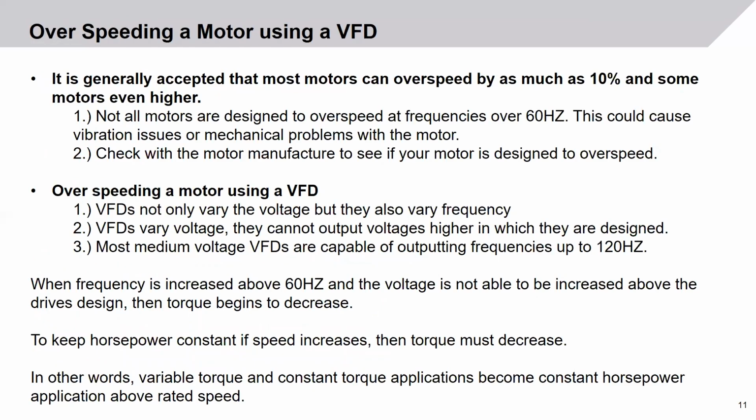It is generally accepted that most motors can overspeed by as much as 10% and sometimes even higher. Not all motors are designed to overspeed, so you should speak with your manufacturer to see if your motor is designed for this.